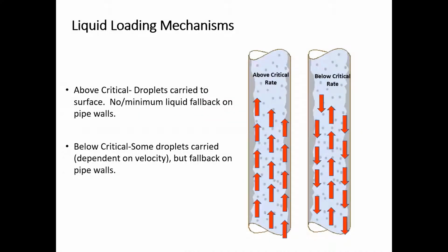Liquid loading occurs when the well no longer is able to flow or maintain a constant flowing condition, and gas velocity, or gas rate, is too low to remove liquids from the wellbore. Why is this? Gas velocities in the tubing have dropped below the minimum requirements to lift liquids from the wellbore. Liquids are falling out of the bottom of the tubing and accumulating.